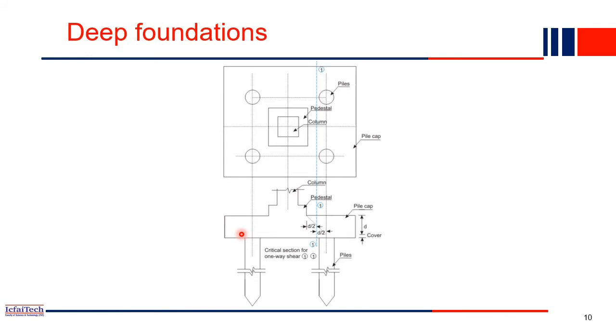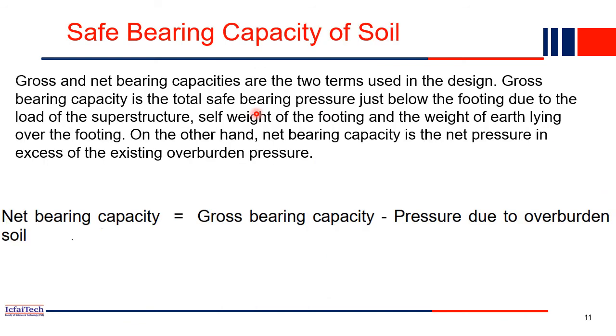So now we have seen different types of foundations, chosen based on the ground quality, meaning the soil properties. If the soil is very good, then we go with a shallow foundation. And depending on the location and the loads, you may go with an isolated footing, a strip footing, or a strap footing, among different types of shallow footing. But if the soil quality is very bad, then we have to go with a deep foundation, make the piles, and construct the structure.